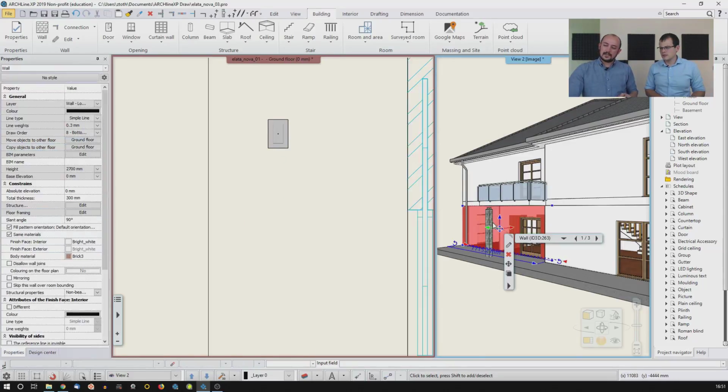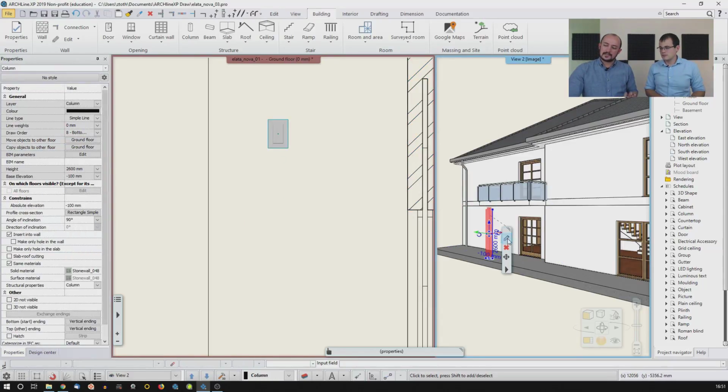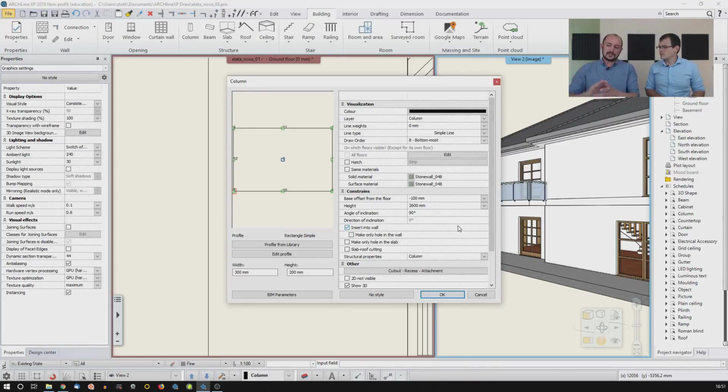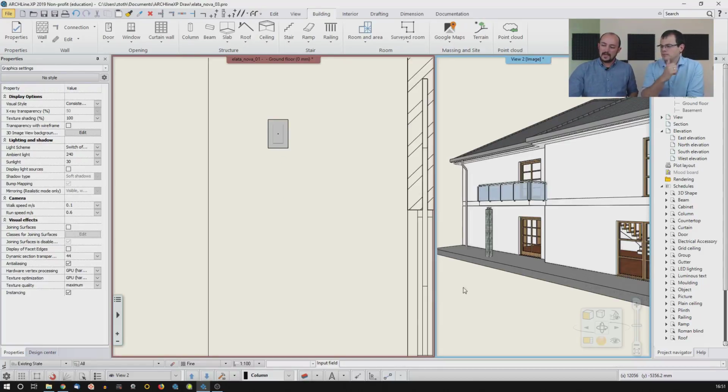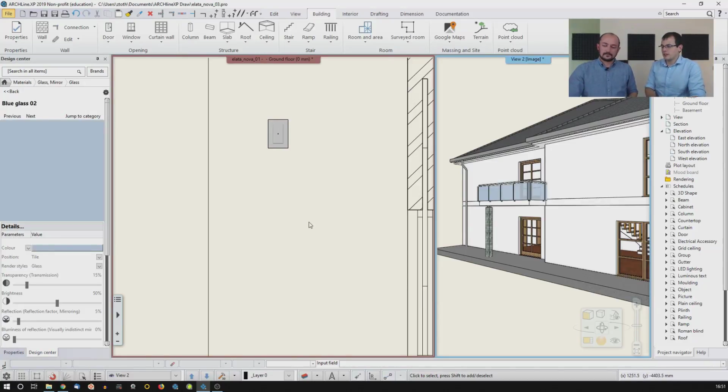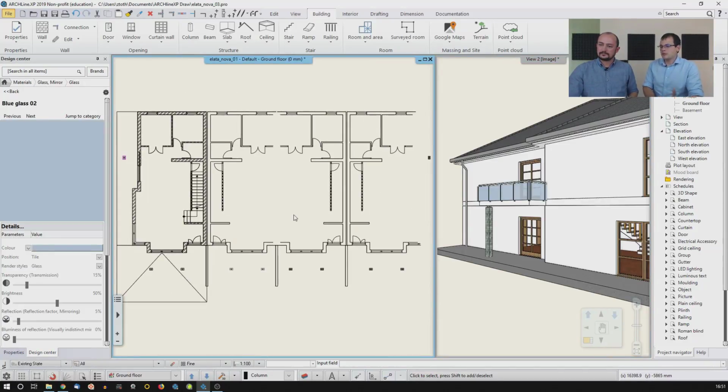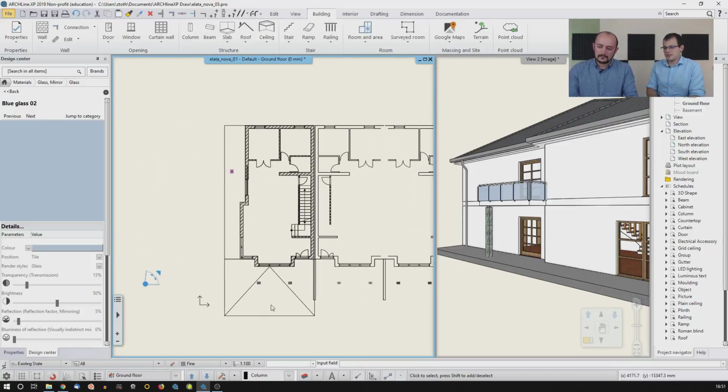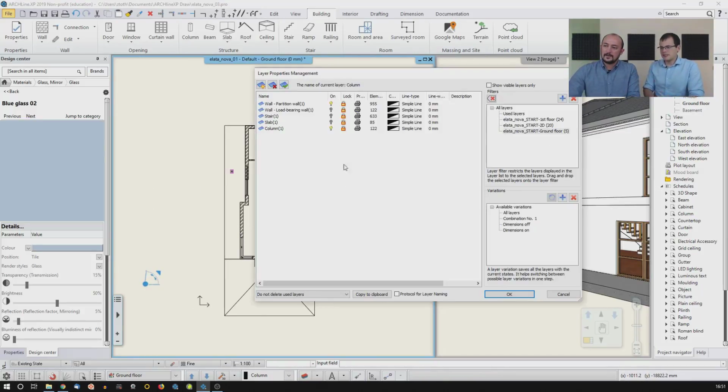And now, see, a tricky thing happened, and this is a default setting for this specific item. It's linked to the floor. I see that the height is now 2,600. It was automatically changed from 2,700, which in many cases is good, but in our case we need to change that to 2,700 to make sure that it really matches that. Perfect. So that is actually how you create columns and elements which have multiple attachments and recesses.